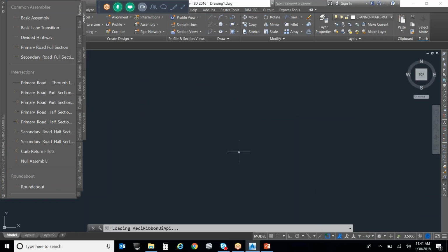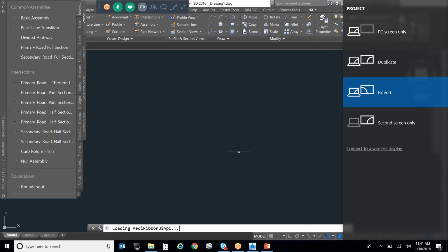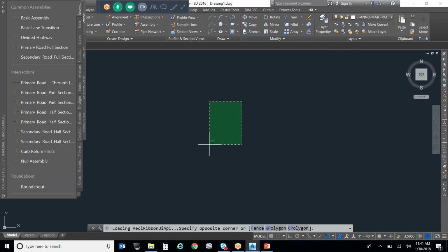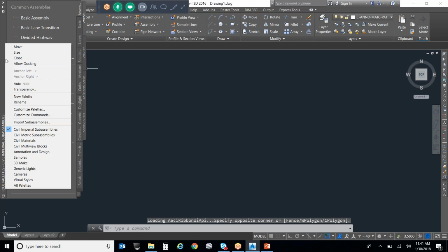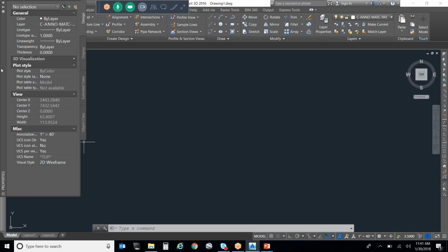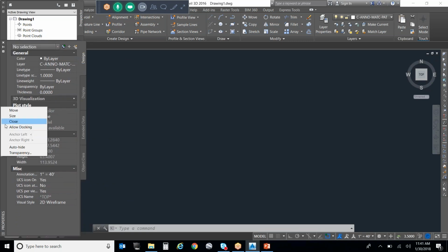Quick question. Yes. Feature lines, so the sites, you have different sites obviously, so the feature lines don't interact with each other. Can you give me an example? I can't recall why you would have multiple different sites in a drawing. Good question. One of the most common cases that I've used that for is, and some of you might balk at this, a lot of times I will actually draw cul-de-sacs as feature lines rather than part of my corridor. And as part of any corridor, you should have a finish surface and also a datum, right?